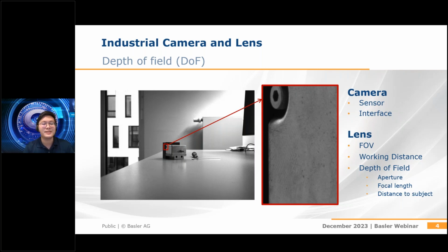In order to achieve high image quality requirements, a higher resolution is needed. Thus, the sensor size and interface speed should be taken into consideration. For example, if I have a large sensor with a high resolution, you require the right interface to fulfill the bandwidth to transfer larger images, right?